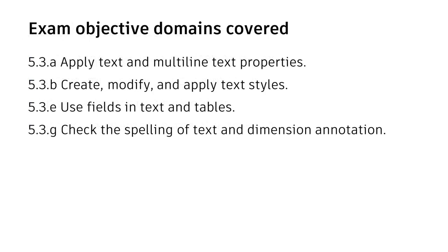To automate text standards at your company, you can add text styles to your company-wide drawing template, making it very easy for all users to follow your text placement standards. Most characteristics of your text are controlled by the text style, including the font, text height, and width factor.